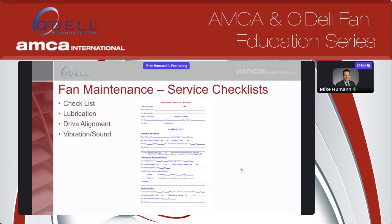So we'll shift gears a little bit here. We'll talk about fan maintenance. I guess the biggest overall thing with fan maintenance is really having a schedule and sticking to that schedule. If you can, audit the fans. If it's not a new fan and it's been in service, it's always good to get out there and get a baseline reading, so you can compare that baseline reading to how the fan is trending in the future. So it's always good to do inspections when you have the opportunity in a maintenance window or a shutdown, or if you're doing some other work on the fan, take advantage of that and get a baseline.